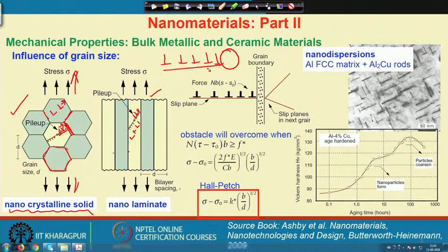So, this will provide us a force value. I have shown a very simple schematic here, and you see this kind of slip plane where a force is built up which is proportional to n, the number of such dislocations, b, the Burgers vector, and the stress difference due to the pile up stress. S 0 depends on other stress than this pile up, like the lattice friction stress.